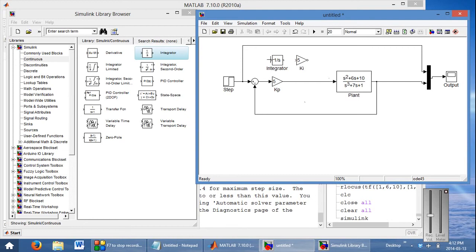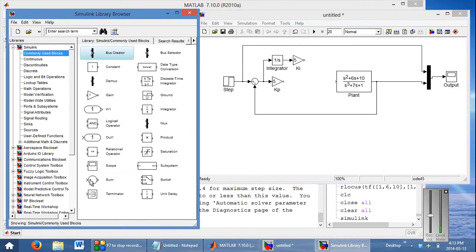So now all we have to do is grab the error and connect all of these blocks. So now we need an additional summation junction in between so that we can add signals from KP and KI. So let's delete this signal and grab a summation block.